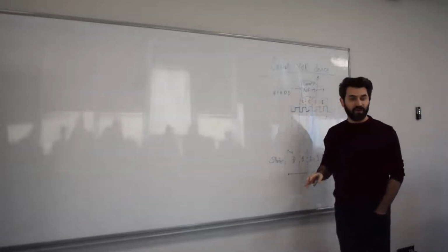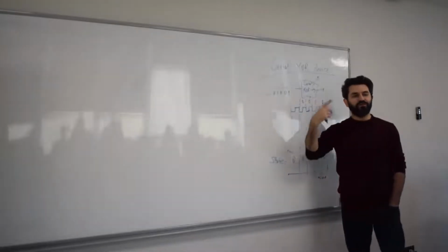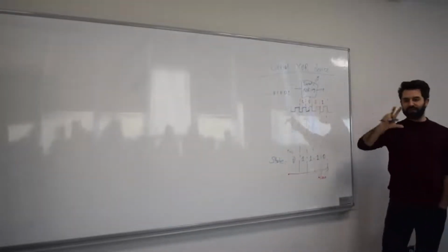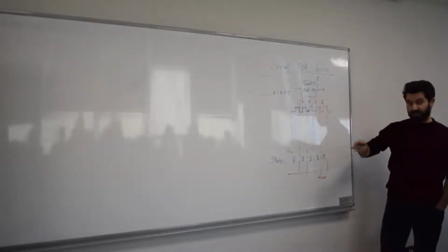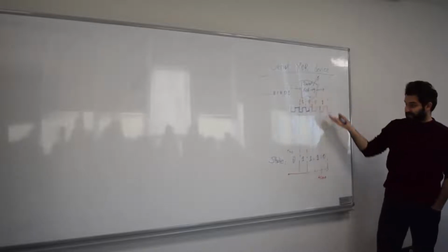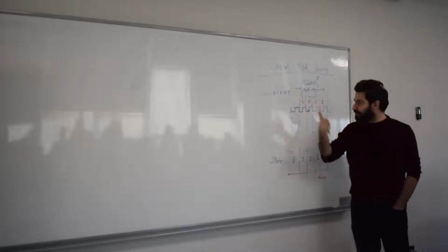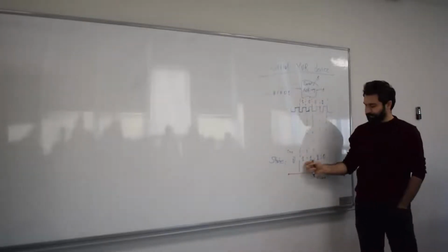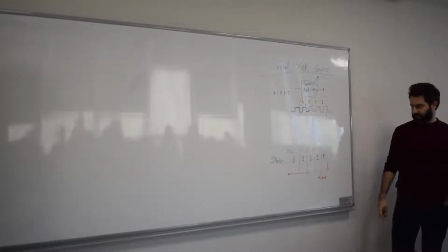It's pretty easy, by the way. It's very, very easy. Just think about how a T flip-flop works. Just look at the functional state table, and you will figure it out. It's quite simple because from a functionality perspective, it's exactly what the T flip-flop is doing. The toggling corresponds to XORing, in the logical, mathematical sense.